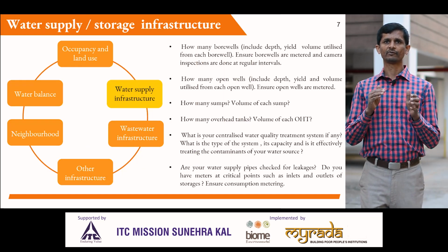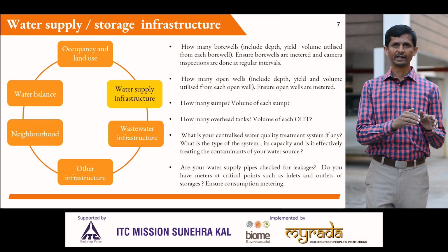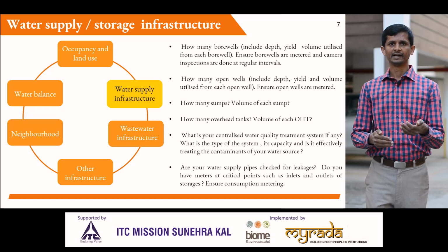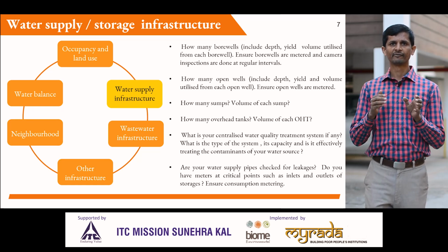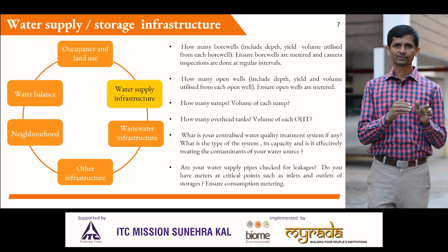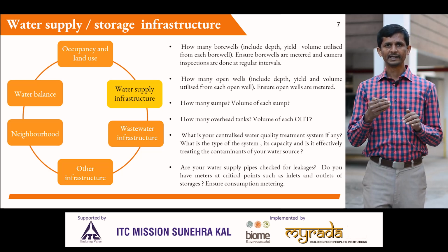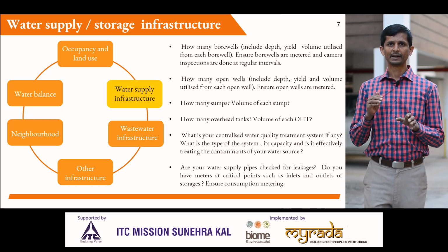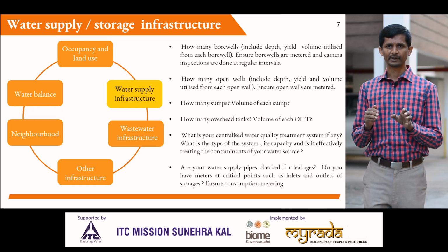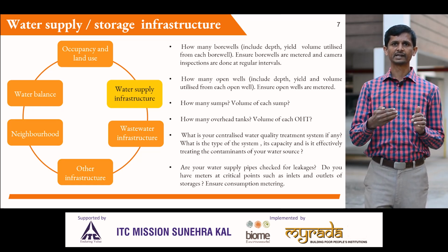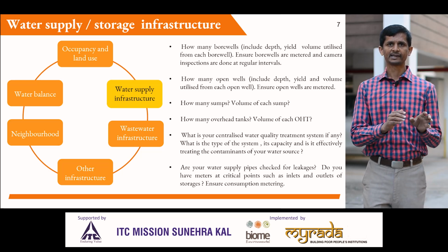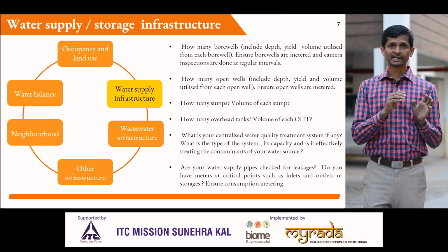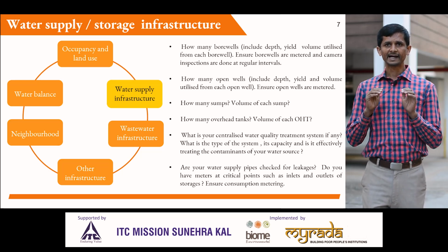What are your different water supply sources? How many open wells and bore wells in your layout? How many are dry? How many are yielding at present? And the volume of water available from different sources. Where do you store all the water and how do you supply it to the individual flats? Is metering done at source like bore wells, open wells, municipal supply to know how much each source is supplying? And at critical points such as inlets and outlets of storages, and consumption metering to know the exact end usage